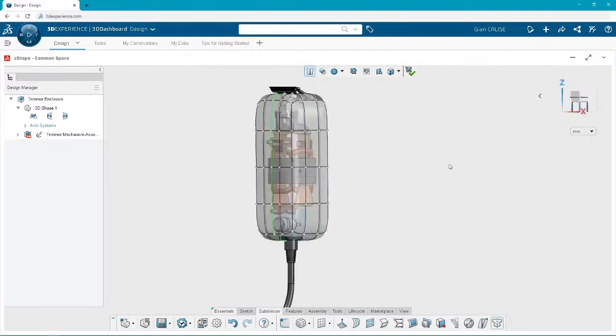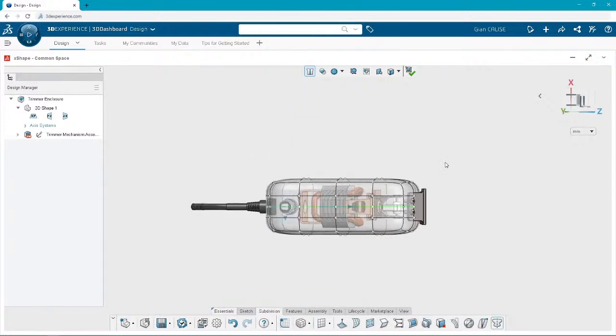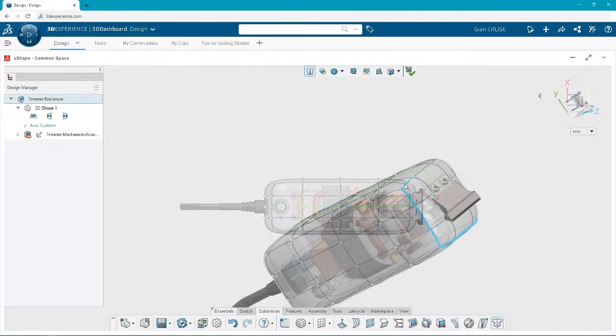Now, clicking any of the faces of that chair allows us to get to that orthogonal view. And I just used the shift arrow keys to switch between different orthogonal views, which you can do in SolidWorks as well. So when you need to jump from profile to profile, that's a huge time saver. You don't even need to worry about using your mouse or anything. Just use your keyboard. That's a big help in X-Shape.